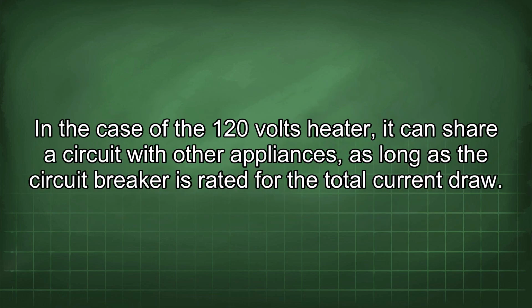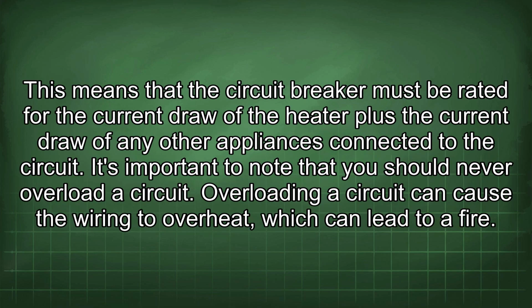In the case of the 120 volts heater, it can share a circuit with other appliances, as long as the circuit breaker is rated for the total current draw. This means that the circuit breaker must be rated for the current draw of the heater plus the current draw of any other appliances connected to the circuit.